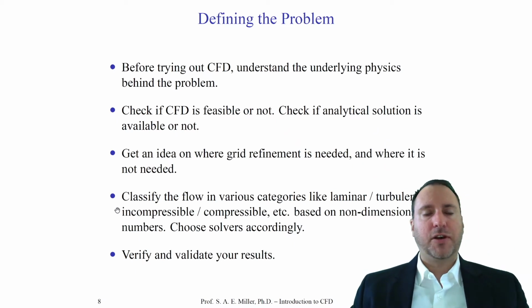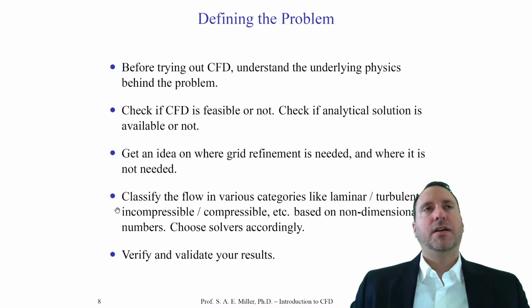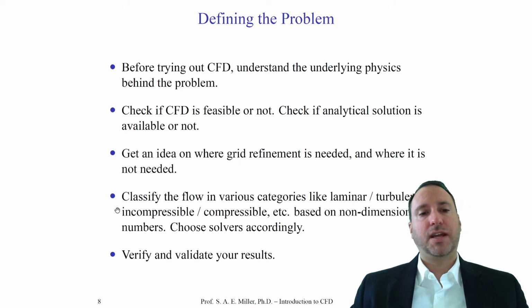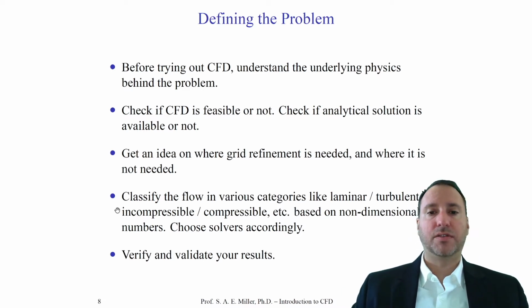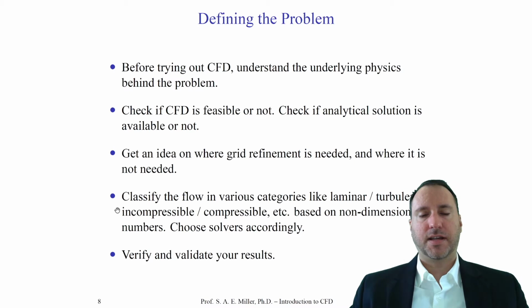Is the flow incompressible or compressible? And this is a huge choice. If the flow is compressible versus incompressible, then you'll have to almost choose completely different solvers in CFD. That is, the way we are solving the equations of motion.